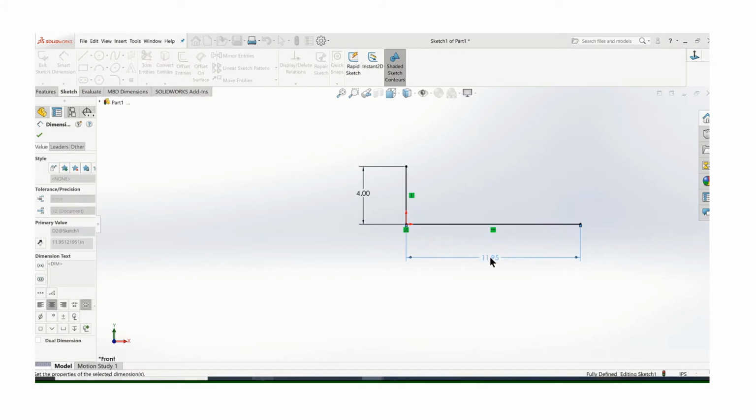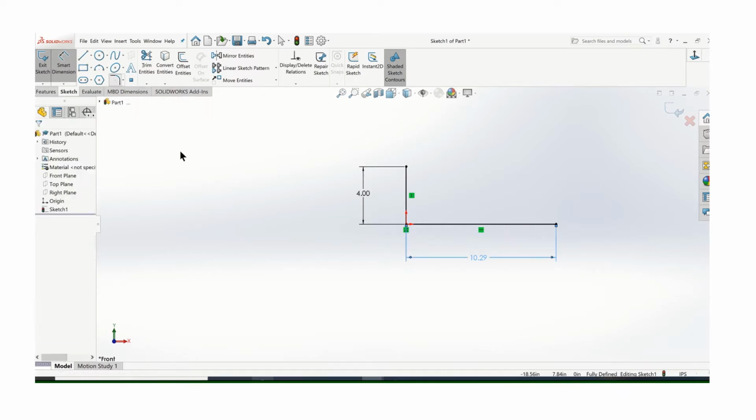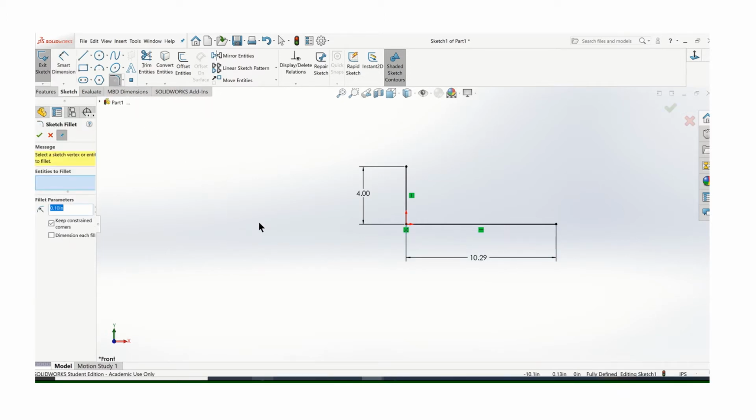Now, this is not my first iteration of this, so I figured out that dimension when I went to assemble it. That's something you'll have to determine specifically as you go to assemble. When you start bending and notching tubing, those numbers won't be nice round numbers, unfortunately. Don't forget, if there's a bend in the tubing, and we're going to try to bend tubing as much as possible here, we don't want just square corners.